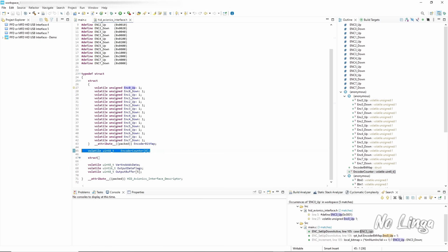Earlier in the series, I mentioned that we are bringing these over, but in the flight simulator, we're not mapping them currently to any functionality because these will count up from 0 to 255. We wanted to reserve that in case we needed to use it when we build a custom driver. And why we would need a custom driver, there's certain things we might want to do in the flight simulator, and we'll end up using SimConnect, whether we're reading data back or entering data within the flight simulator environment.